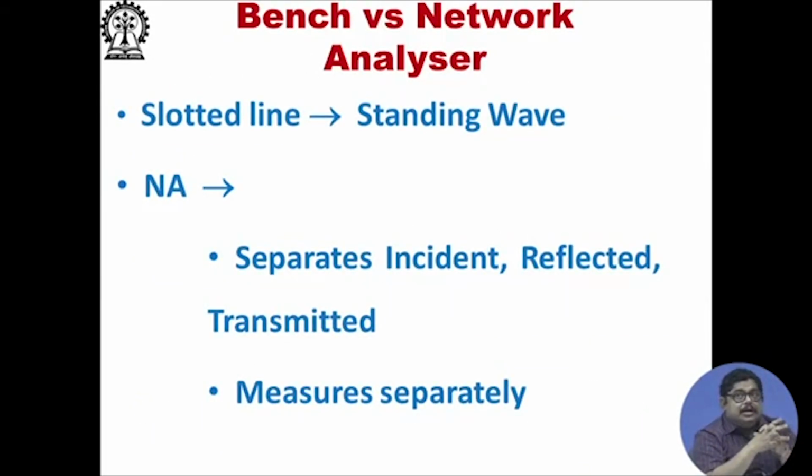Now, the network analyzer's predecessor was the microwave bench. We have seen microwave benches in the impedance measurement lecture. Basically they work on standing waves. Network analyzers don't work on standing wave phenomena. They can separate incident, reflected and transmitted waves. So, they measure these incident, reflected and transmitted waves separately, and that is the beauty of the network analyzer.